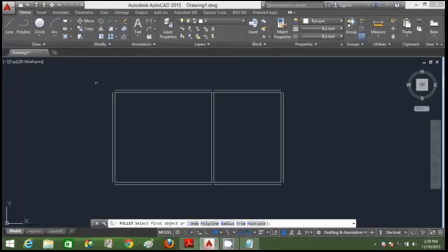Right, and I'm going to use fillet now to join all the unjoined lines. Click fillet and click this line, click the other line to join it. Alright, so I'm just going to use line command just to extend this, in order to close that loop. Alright, click fillet again and join these two lines. Fillet with radius 0. Okay, click fillet without defining any settings of a radius, and just click both lines.